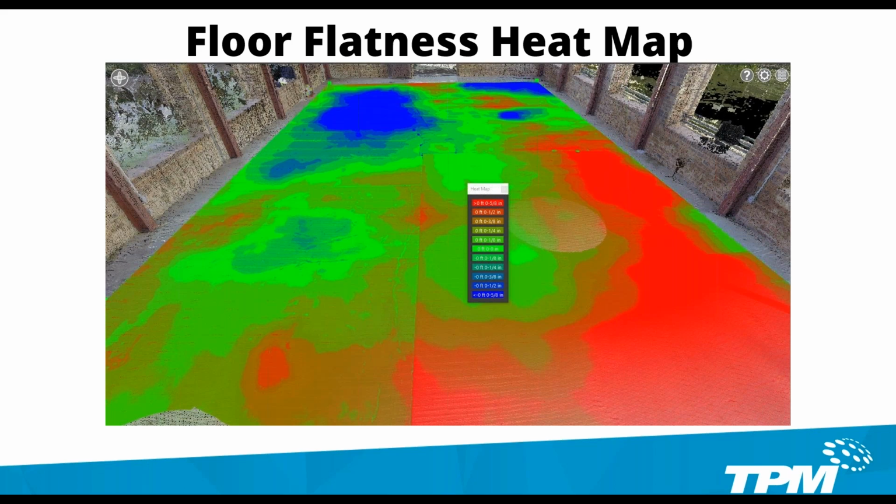I've seen this type of image used to help explain a design issue and a change order related to floating a floor, and having a unique situation that we needed to get everyone involved around. We had the laser scanning data and threw that into our software here, and we're able to quickly produce a heat map to make some decisions very, very quickly. So with floor flatness, we're able to take all that point cloud data, compare it, and give us this type of output.